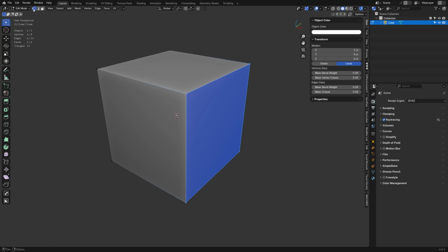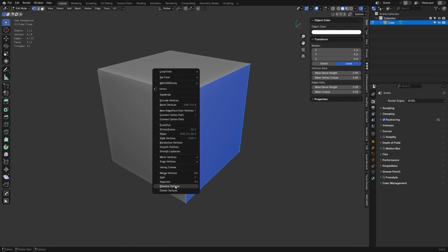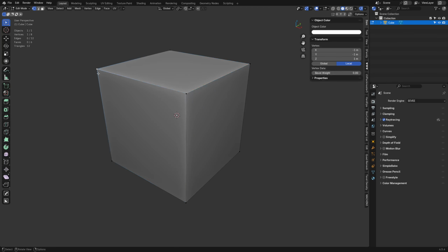It's dynamic. Every time we switch to a different mode, it's going to update with different tools. So you've got to pay attention to this up here, and that'll help you out quite a bit. Now, of course, selecting things: shift selecting will select multiples. Whatever we shift double tap on, you see how it highlights, that's an active element. We might actually end up using that. I don't know yet, but sometimes you can use the active element to align things. Then A to select everything, and double tapping A to deselect everything. So you'll be able to do that very fast now.